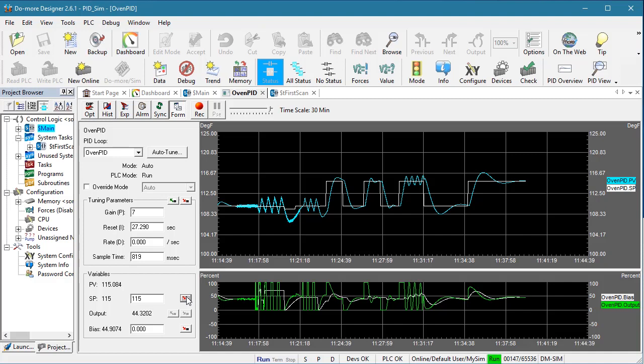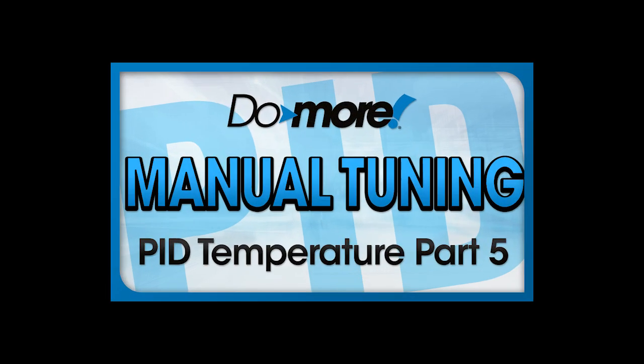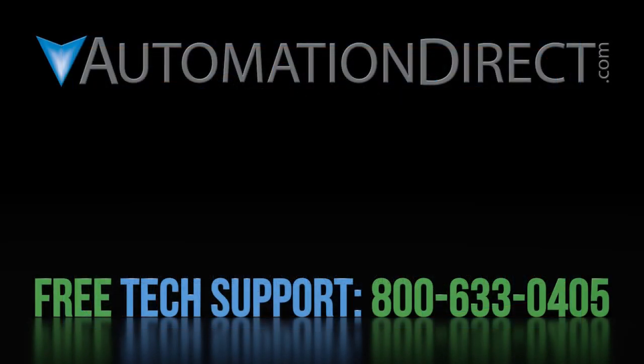Nice. AutoTune on the Do More PLC works really well, but it can only do so much. Things like system noise can have an enormous impact on AutoTune, and if you have an odd system response like this, well, AutoTune may not be able to give you optimum results. In situations like these, it's really helpful to know how to manually tune a PID loop. In the next video, we'll show you a quick, easy, and reliable way to manually tune a PID loop. It uses an open loop tuning method, so we'll also take a look at the Do More's open loop tuning for comparison.